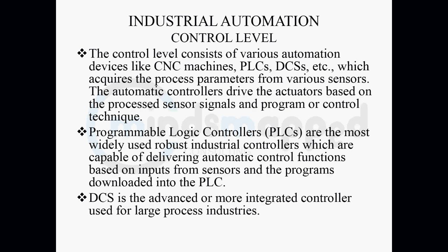The controller evaluated this input and made this input tag high. Once it does that, it evaluates that if this input is high, I am supposed to make this output of this motor high as well. And it made that output high. Then the output sends out the 24 volt to the contactor, then to the MCC panel, and then to your motor, which in turn starts the motor.